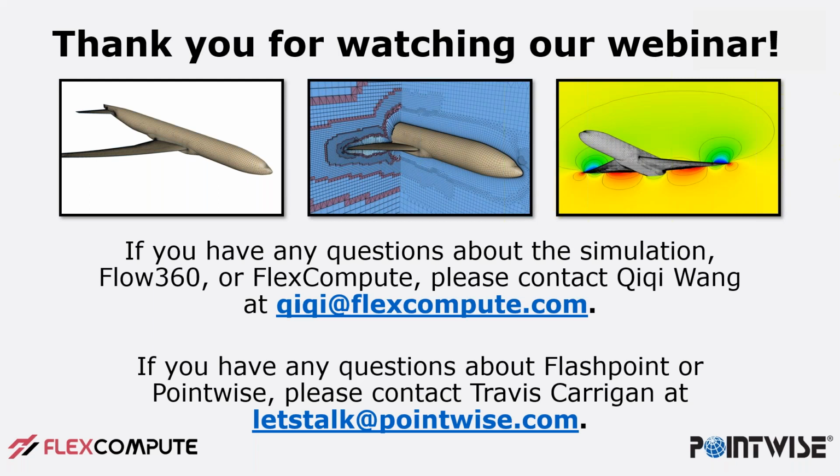Are there any restrictions on mixing concavity, convexity of the databases? For instance, if modeling an airplane with an inlet. The only thing I'll say there, and maybe that would be something where you can reach out and we can take a look at a specific example, is it comes down to quilting. So as long as you have your geometry quilted properly, and what I mean by that is quilt boundaries exist where there are hard breaks in the geometry, right?